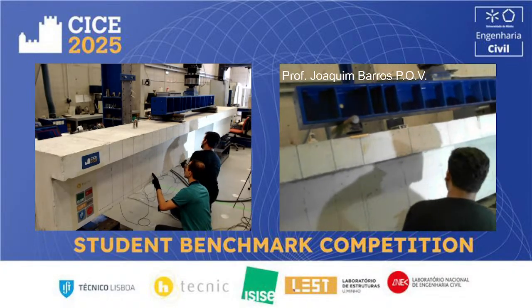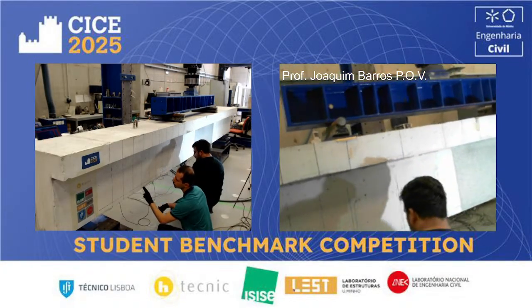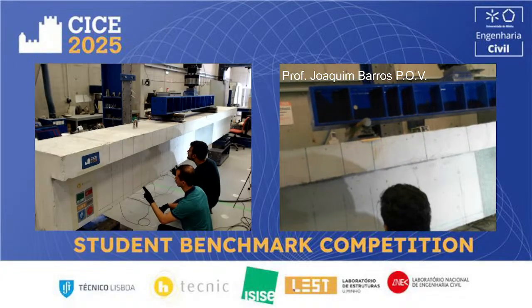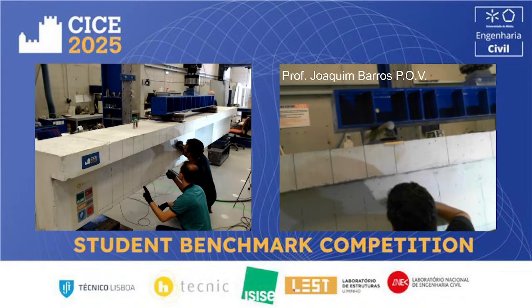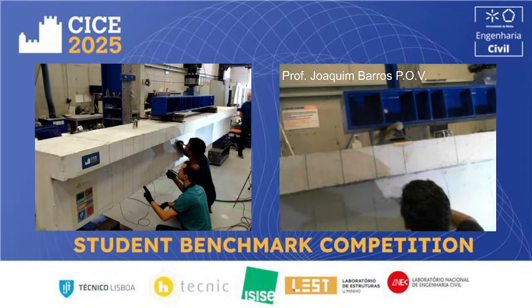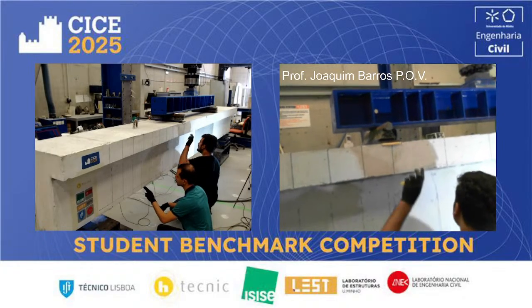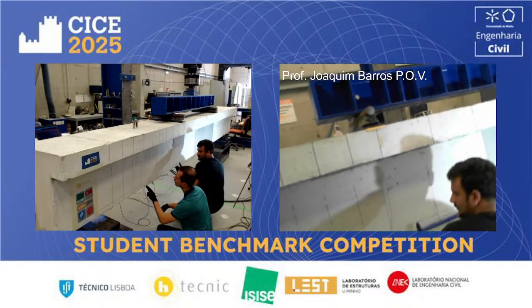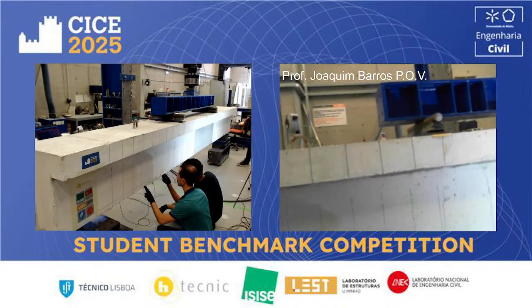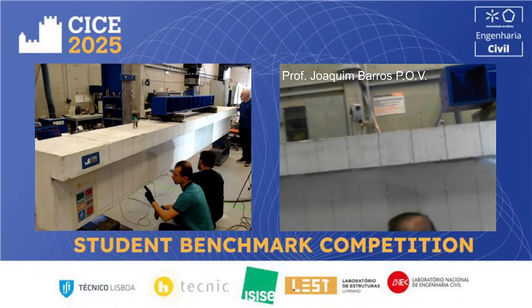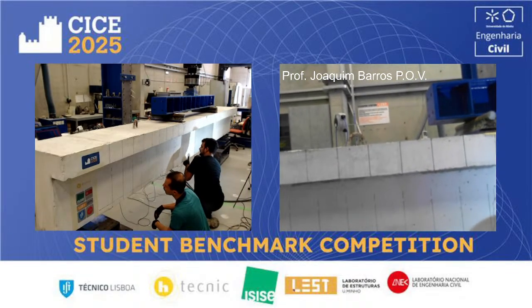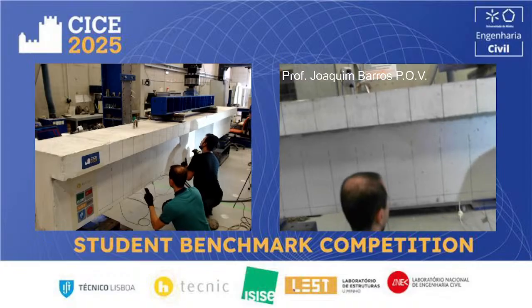So all the cracks up to the moment were formed in the pure bending region, if you neglect the effect of the dead weight of the beam. So apparently no cracks have formed up to now in the shear span.